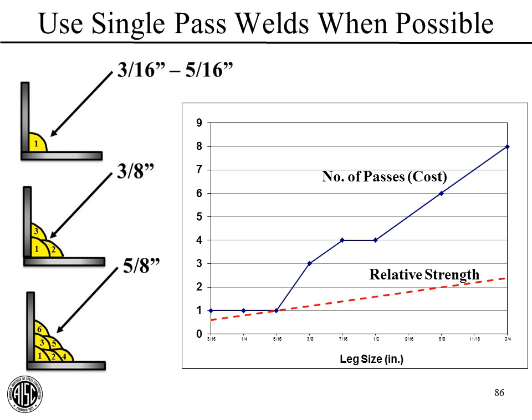Okay, just finish up with a comment about something we can be thinking about. Pretty simple during design is the effect of the number of passes and the fillet weld size. Let's say we have a 5/16 fillet weld. This can be laid down with one pass. Okay, now if you have more passes, it's obviously the price is going up, the cost is going up.